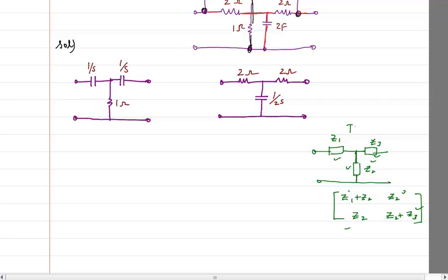And this is basically called a T network. Don't confuse it with T parameter. Many of you have confused this with T parameter in your examination paper, your series test. Please don't make that mistake. T network is different, T parameter is different. Here this is called a T network because it has the shape of the letter T. Whereas T parameter is the ABCD parameter.